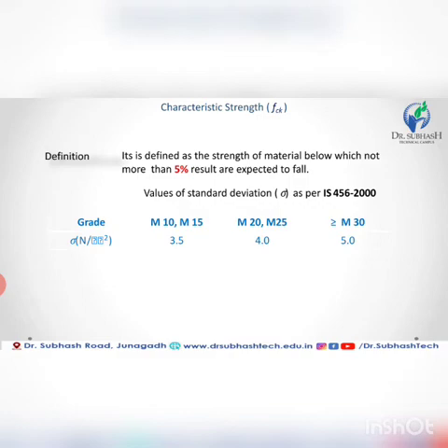Value of standard deviation by grade, stress in Newton per mm square, as per IS 456-2000: M10 to M15 is 3.5, M20 to M25 is 4, and greater than 30 is 5.